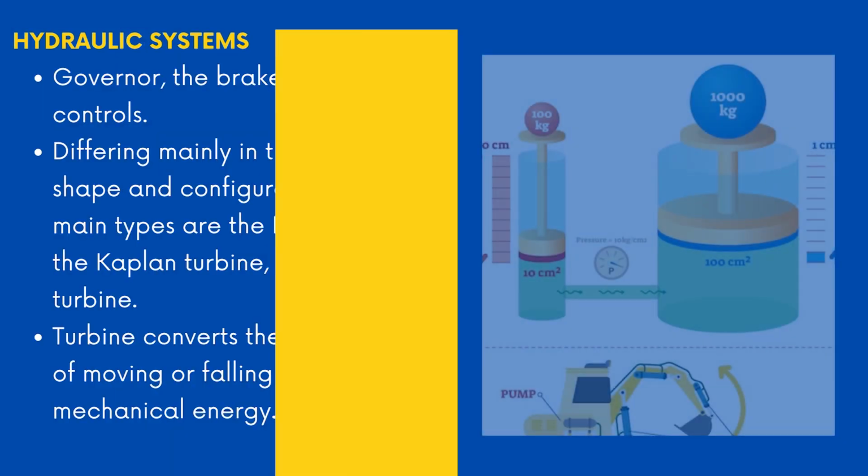Water from the reservoir is delivered to the turbine through the intake and penstock. A filtering system at the intake further cleans up the water to ensure that it is relatively free of suspended solids which could damage the turbine blades. In my PPT that I will share with you, you will find a clear diagram indicating all these structures. Now let us go through hydraulic schemes.